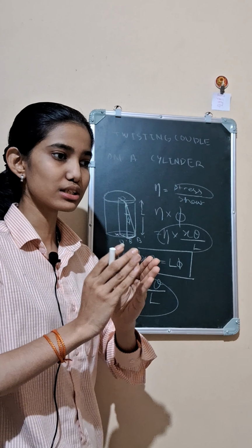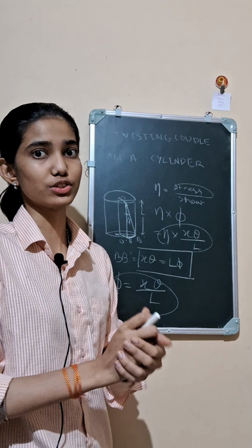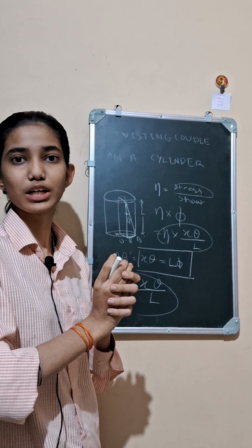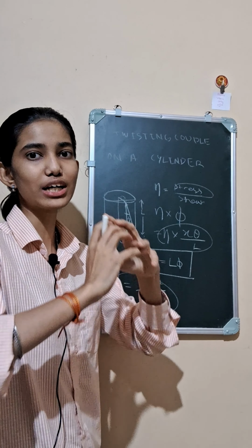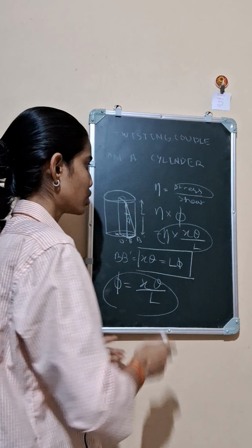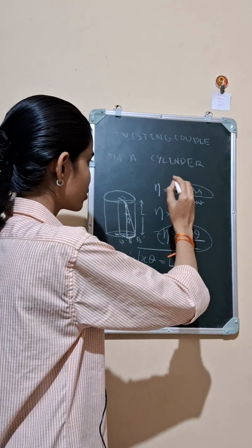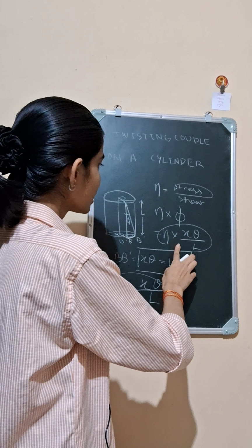We have considered that the solid cylinder is made up of many hollow cylinders, and have taken this one in particular where the radius is x. So this is an element of that big cylinder, not the cylinder for which we are calculating this. So for this elemental cylinder, here is the stress.